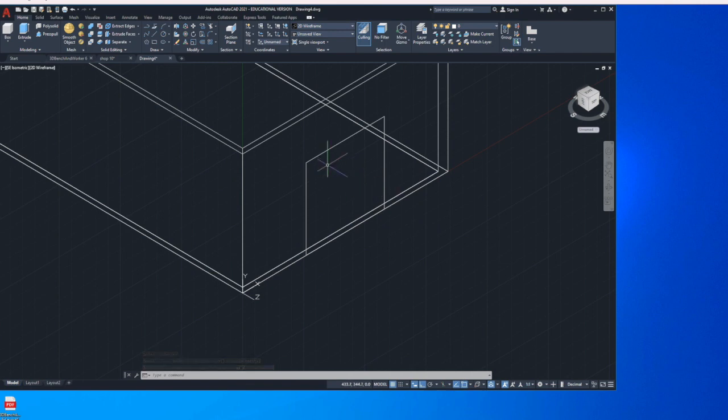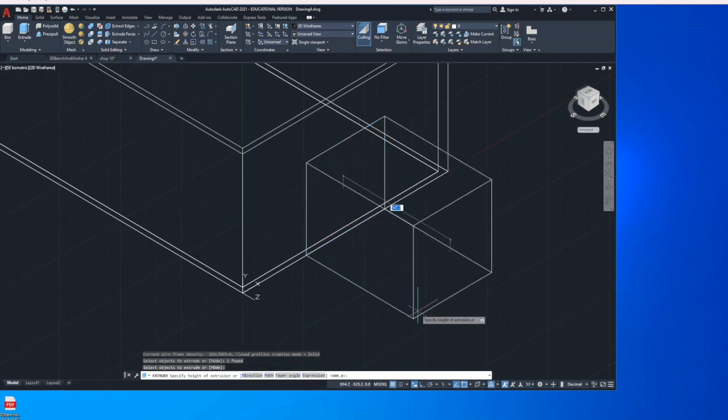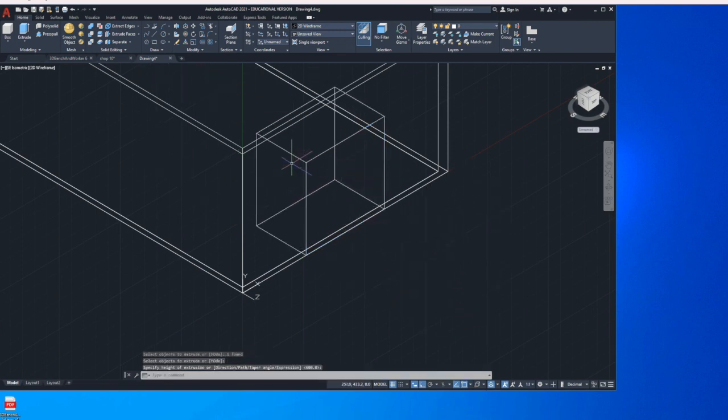But the door is just an outline on the surface. So I'm going to use the extrude and subtract tools to punch a hole in the wall, basically. So I will go to extrude again, and I will select the door outline. I'll type return, and now I can go either way. I'll just push it in, and I'll type return. So now I've got this box protruding into my building.